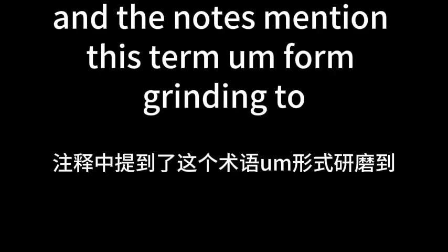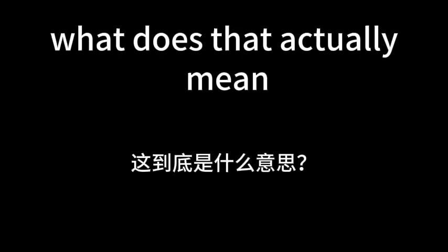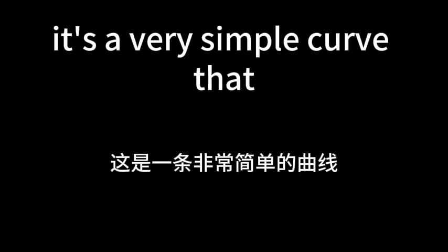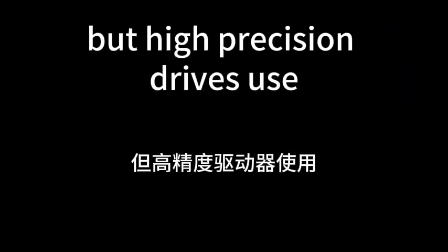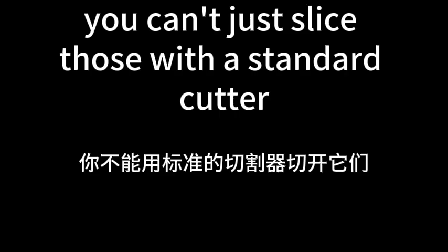And the notes mention this term form grinding to bypass what they call standard involute limitations. What does that actually mean? Well, most standard gears use an involute shape. It's a very simple curve that standard machines can easily cut. But high-precision drives use highly complex, unique curves. Like the epitrochoid teeth on a cycloidal disc. Exactly. You can't just slice those with a standard cutter.